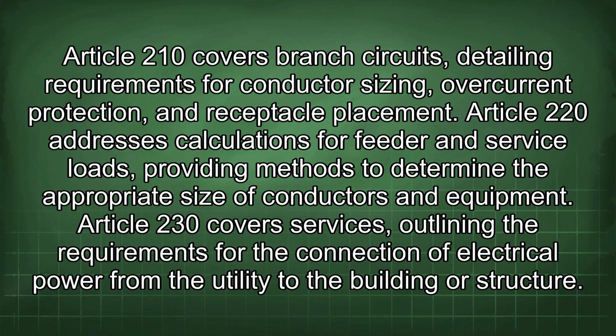Article 210 covers branch circuits, detailing requirements for conductor sizing, overcurrent protection, and receptacle placement. Article 220 addresses calculations for feeder and service loads, providing methods to determine the appropriate size of conductors and equipment. Article 230 covers services, outlining the requirements for the connection of electrical power from the utility to the building or